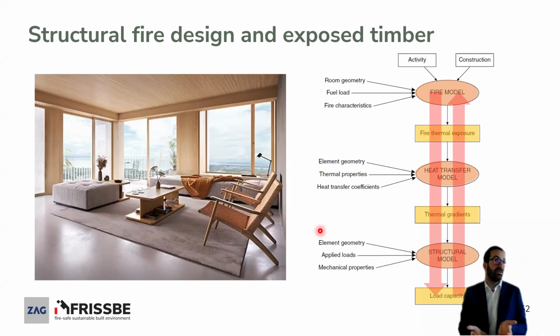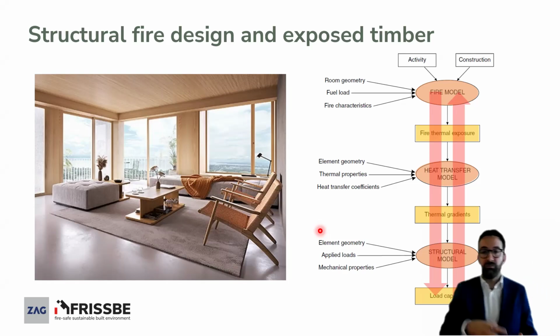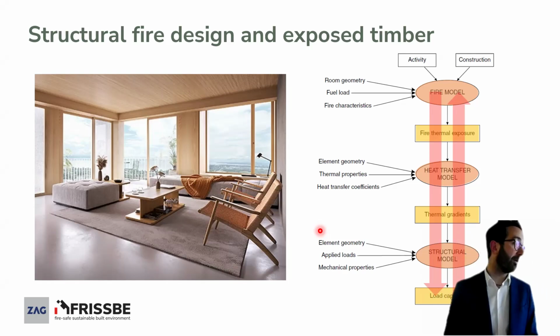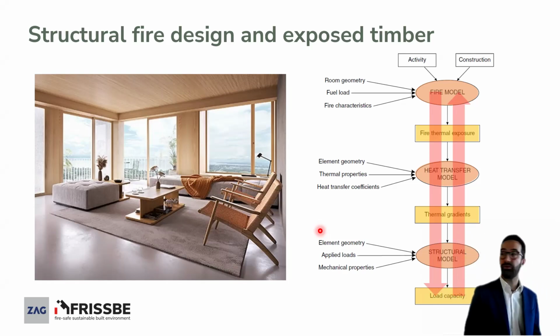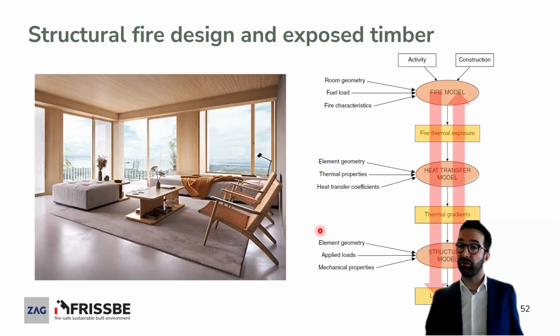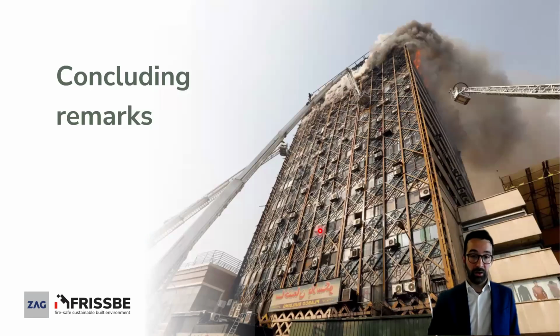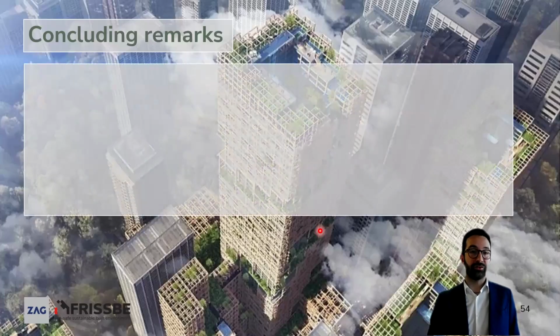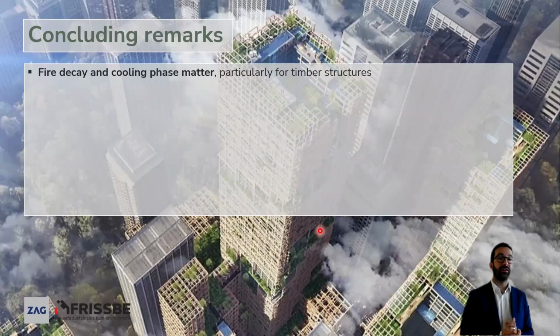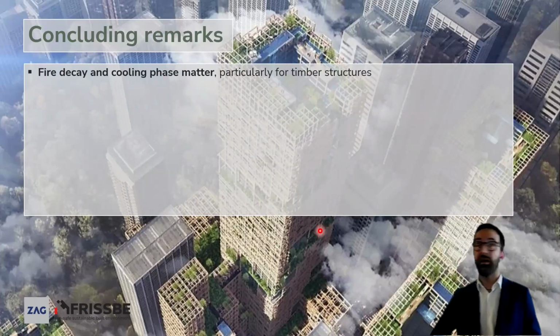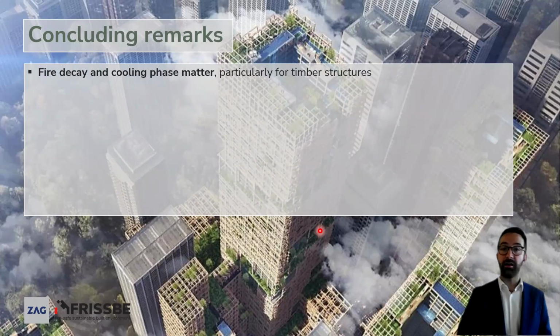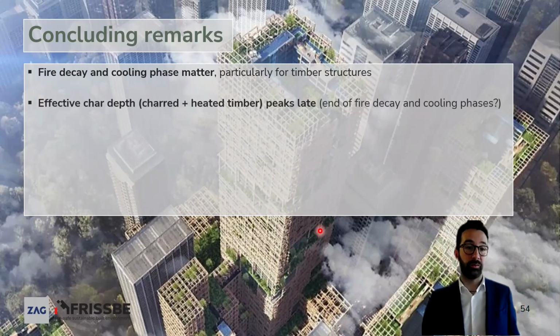So you have to make sure that, first of all, you can define an appropriate fire scenario that would let you do an appropriate structural engineering analysis for your element. To conclude, I wanted to mention today that the fire decay and cooling phase matter, particularly for timber structures, and I hope today I explained to you why it matters and how it possibly would matter.